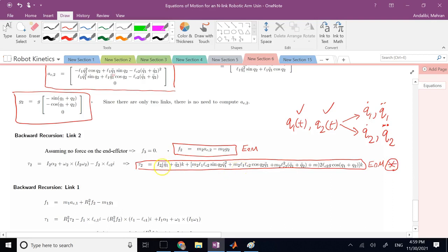And in that, with tau 2 and tau 1 given, I need to solve for the double dot terms. That gives me differential equations, 2 second orders. If I can decouple them and solve separately for them, then through the numerical solution of that with the taus given, I can find Q1 and Q2 and the dots all numerically, and then I can plug them back into this equation, and that gives me the values of the force numerically.